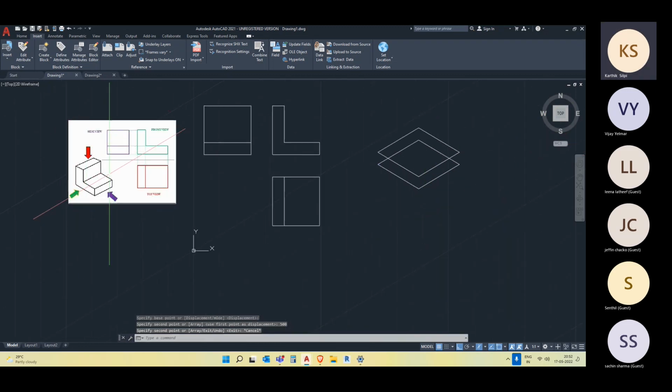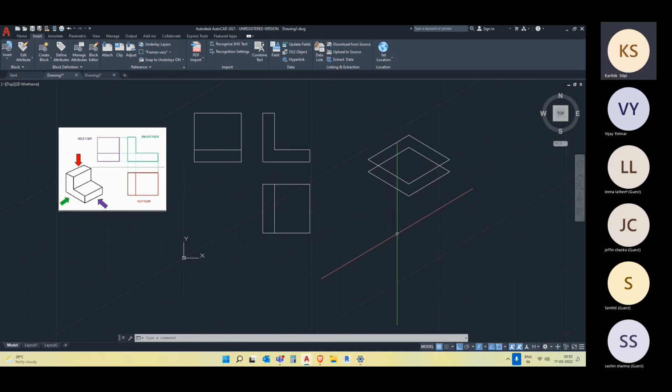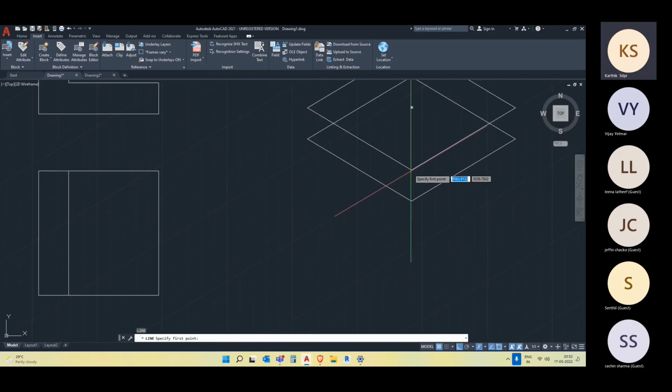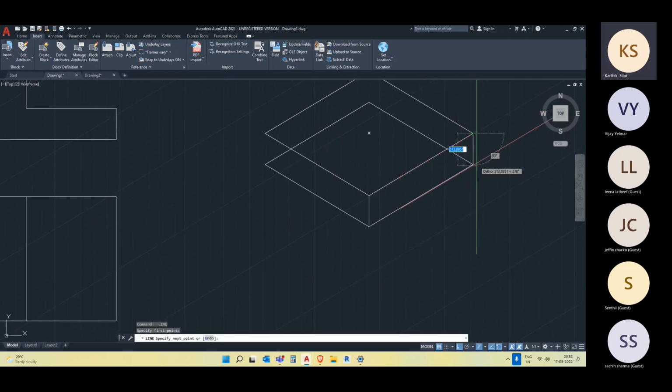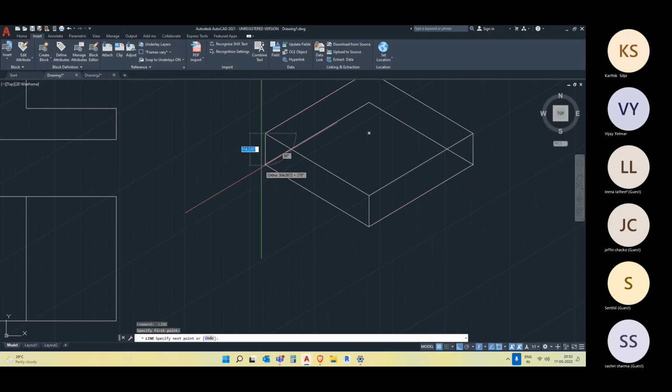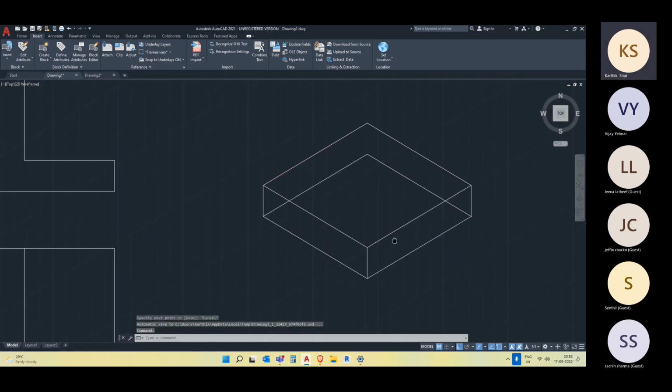So we've got this surface, but is it correct? No, because we have to have a partition over here. That partition should happen 500 units from this distance. Okay, that's what we know. First, let me connect all the edges. I'm drawing L enter and then just escape, spacebar again. That command will continue wherever we left.